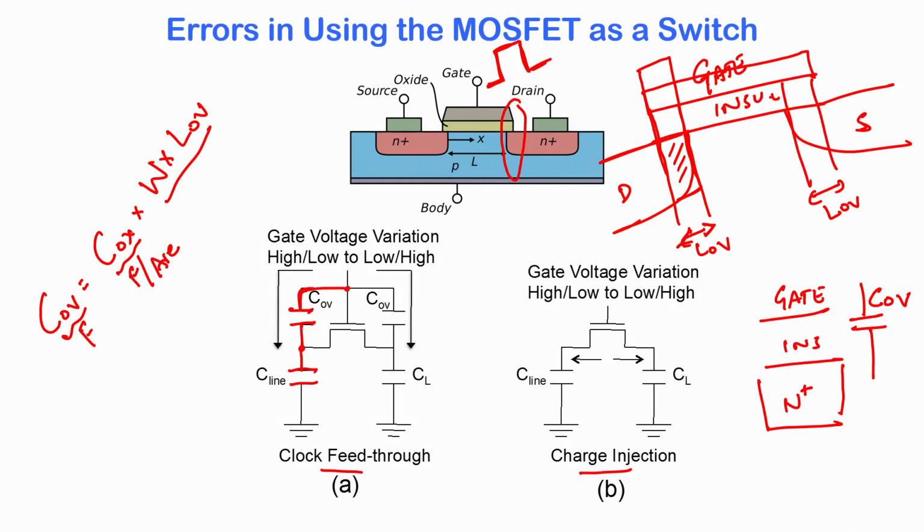Okay. So, if this were to be your circuit, if this is the switch capacitor circuit that we are looking at, let us say that is the capacitor and we are observing all the voltages on this capacitor, and we saw that there were some blips coming in and going out. So, the circuit that should actually be drawn is the circuit with this overlap capacitance between the gate and the drain.